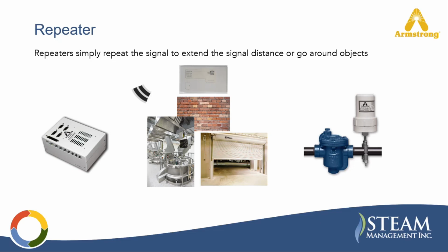They are commonly used when transmitters are located a long distance away from the gateway or when physical obstacles such as buildings, equipment, tunnels, walls, or other structures interfere with wireless communication. Rather than running wiring all throughout the facility, repeaters allow the network to expand wirelessly while maintaining a strong communication path back to the gateway. They are particularly useful in those larger facilities, district energy systems, campuses, and facilities with underground vaults and tunnels where direct communication may be difficult.